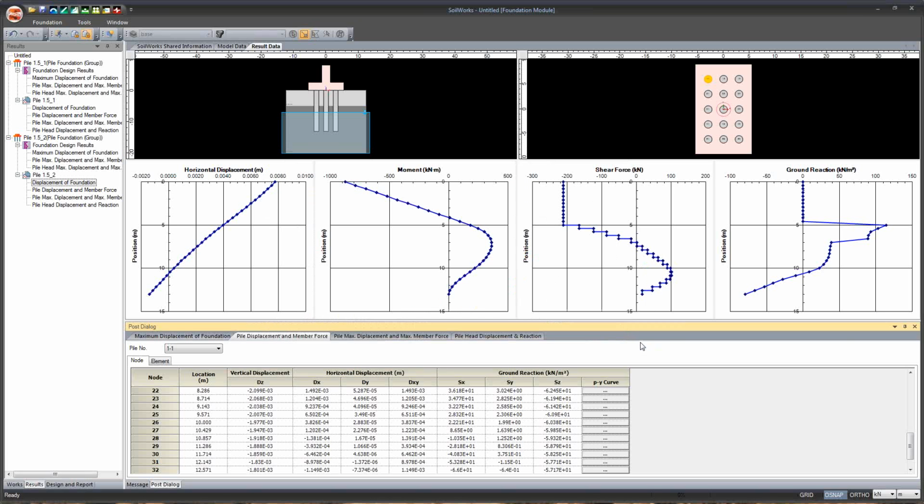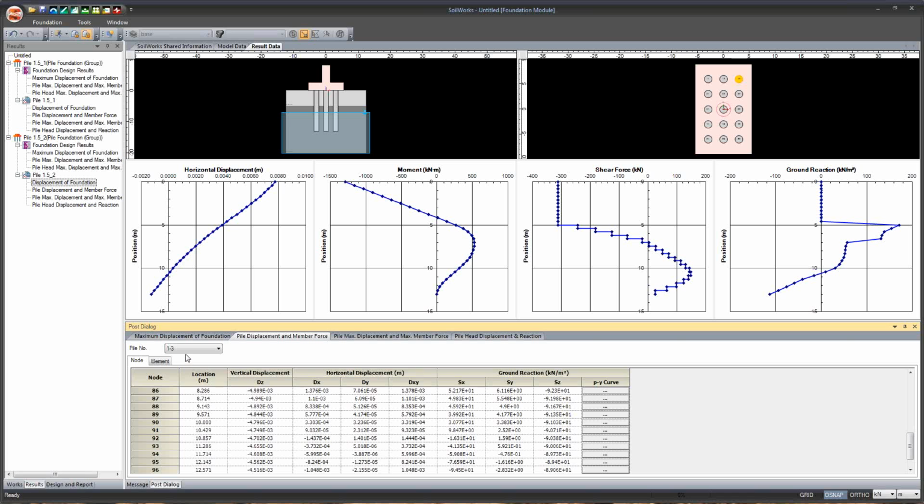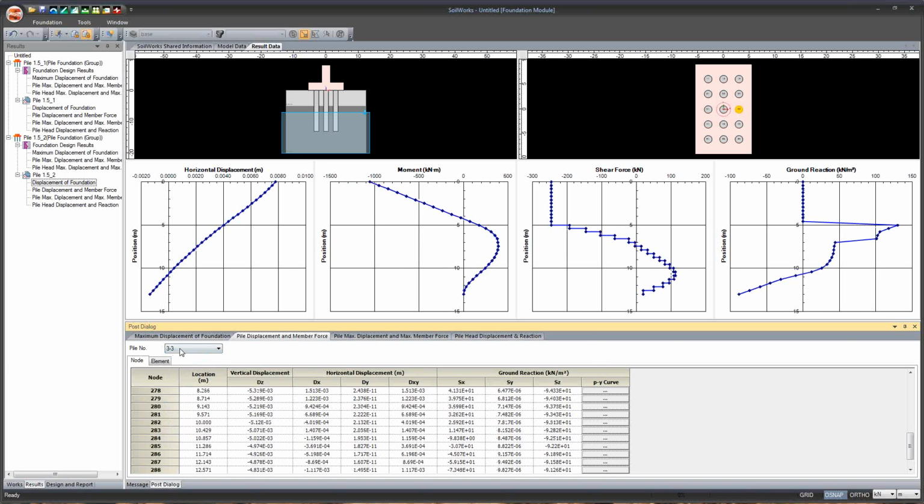As I already told, if you are not considering the non-linear behavior of soil, then there is a huge difference in the simulation of what you are doing. So you can get the behavior with the different model types, how exactly each spring is behaving, and you can provide the stiffness at that particular location for each of the piles. You can just change the pile from here and you will get the pile stiffness or pile PY curve, to be exact.